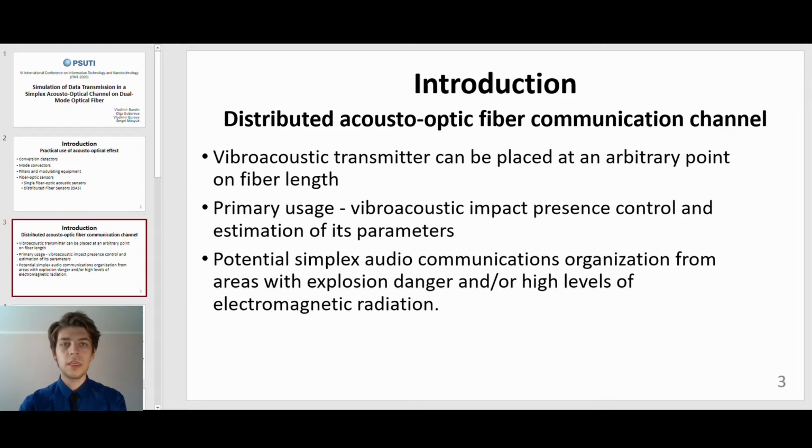As a rule, such ways, as well as the reflectometrical ones, are based on the reception of very weak backscattered and reflected optical signals. To significantly raise the received signal level, there are ways based on the reception of optical emission spread forward in multimode optical fiber. There are well-known distributed acoustic sensors on multimode optical fibers, for which the target evaluations are obtained according to speckle analysis results.